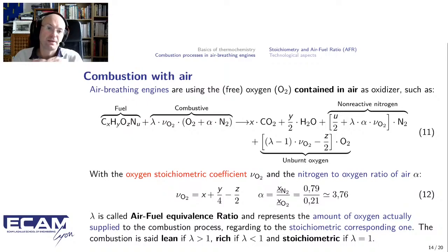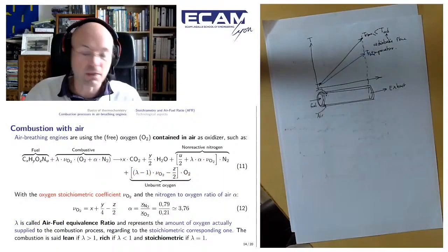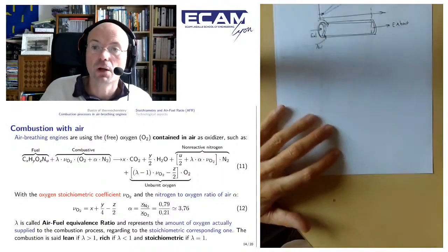And I know that here, whatever the temperature or the pressure, I always have 21% of oxygen and 79% of nitrogen. This is the standard air we will use in the rest of this combustion. Because you have 21% oxygen and 79% nitrogen, in molar fraction, when you have 1 mole of oxygen, you always have 3.76 moles of nitrogen. The calculation is really not complicated, but it's important for you to have seen it at least once.